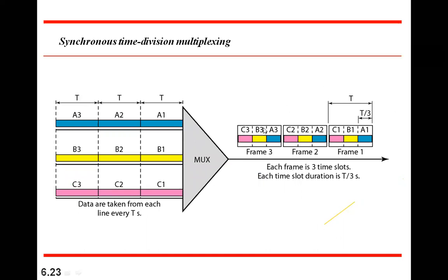Okay, so what is this? This data rate is n times faster, multiplied by 3 times any of them, right? But at the same time, when the data rate increases, the duration of each of them is automatically reduced. So it becomes one third, compared to the bit duration here and the bit duration here. If you compare, this will be one third of any of these. Then only this TDM will work.